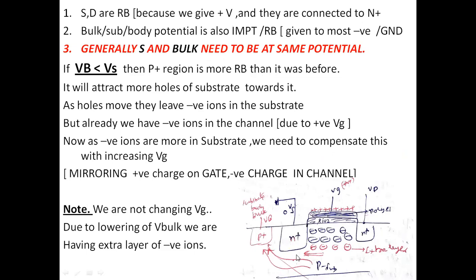This is the normal figure like what we have seen while discussing the operation of a MOS device: accumulation, inversion, and depletion operations. We have here the source terminal, the drain terminal and the gate terminal. Along with that, this SiO2 layer acts as the insulator layer between the gate and the channel, and we have the polysilicon material, from which I'll be taking the gate terminal.